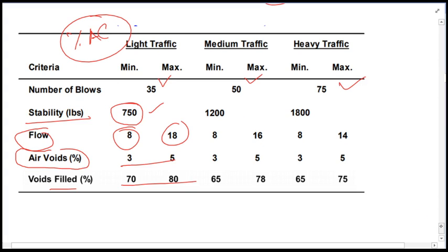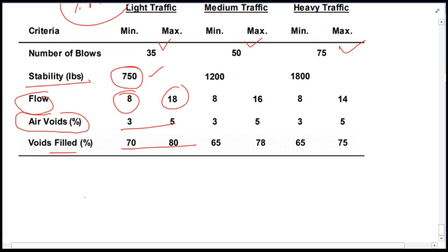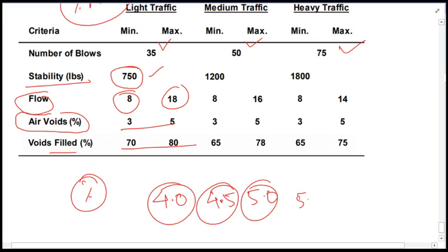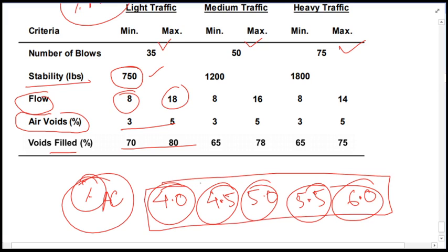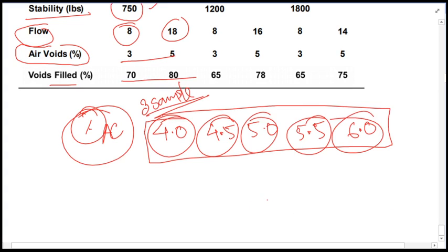So that's why we started to first fix the asphalt content. We are taking 5 asphalt contents, and for your experiment as well you will take 4%, 4.5%, 5%, 5.5%, and finally 6%. For these 5 asphalt contents, 3 samples for each will be created for this test, and from those, average values of stability and all other things will be taken. That's how you'll have to proceed.